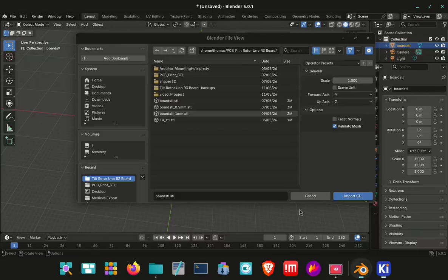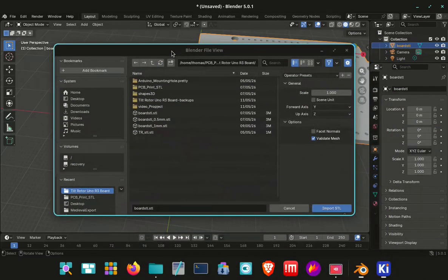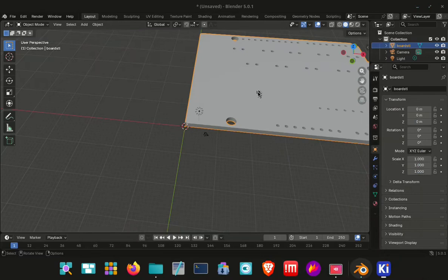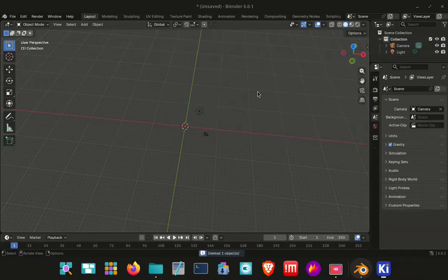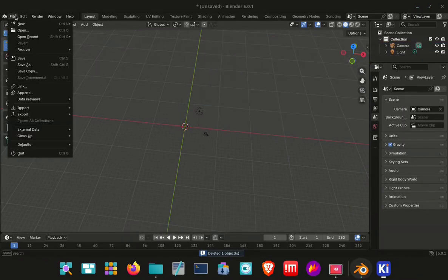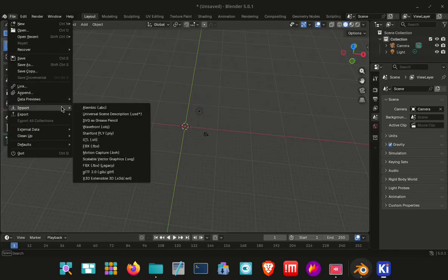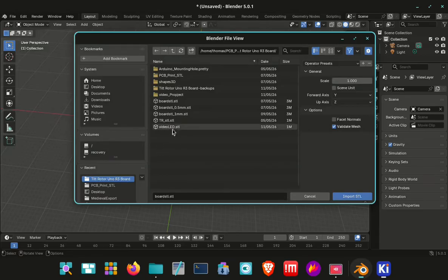I'm going over to Blender. Now, delete that. Okay, so file, import, STL, and here we have video LED.stl. If you ever find that it doesn't import the .stl, make sure that it is just ending the export with .stl on the end and not .stl step and all of that good stuff, as you saw me delete there.